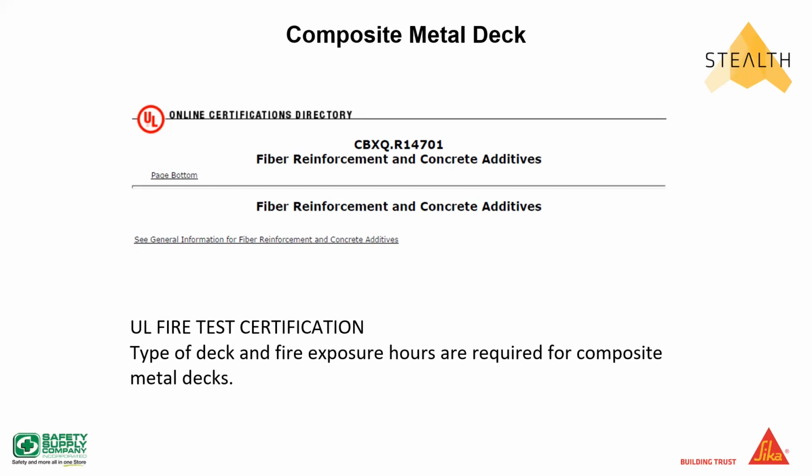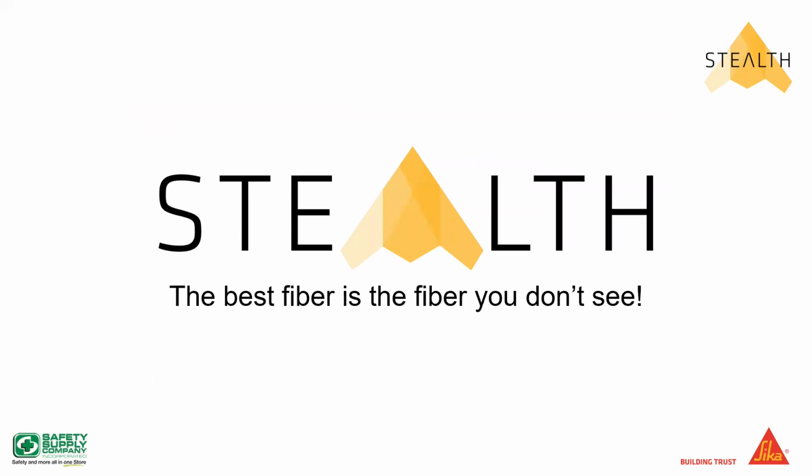What I will tell you is we don't do what I refer to as a true supported slab. We will not replace the steel in a self-supported slab, meaning that they've got rebar in the concrete. There's no decking or anything like that, and we don't pull that out and replace that. That's a no-no for the fiber industry. But again, the metal deck applications, absolutely, that's big business for us.